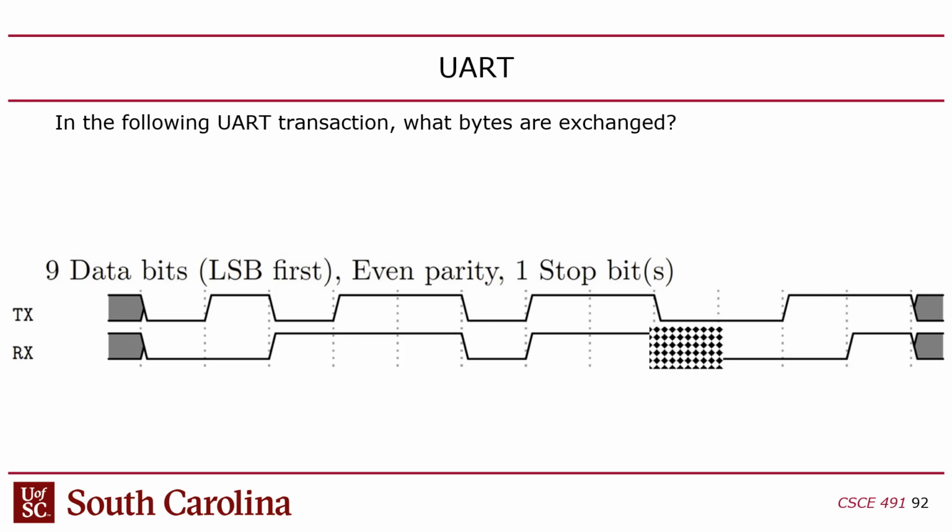We could find out. If you look up the data sheet on the Atmel 328P, there's probably a flag in the status register for that, is my guess. So you could probably read one of the status registers. Remember the example I showed you where I had a flag that said, is the peripheral on fire? And there was a bit for that. There's probably a bit in the UART address space that says error. That's my guess, but that's a great question. I haven't thought about that. From the software perspective, I'm not sure how you check that.